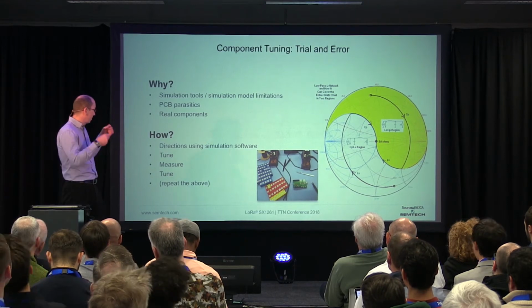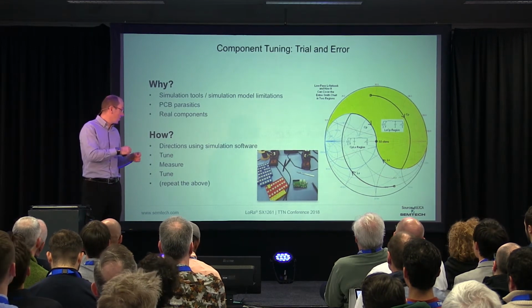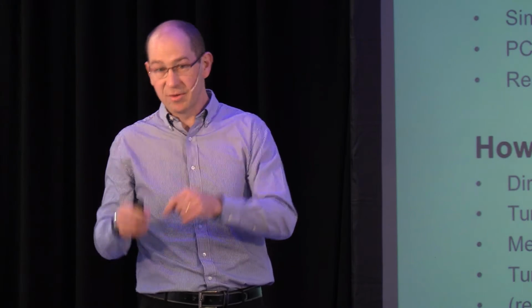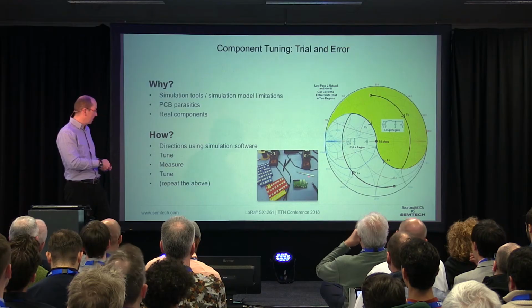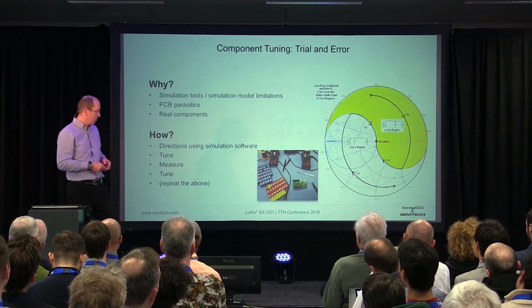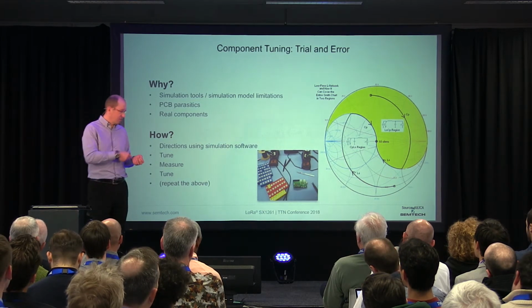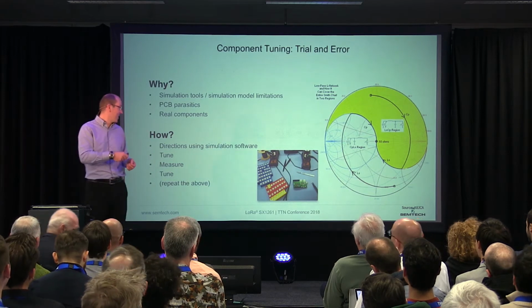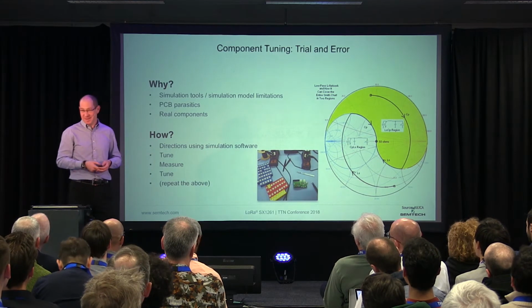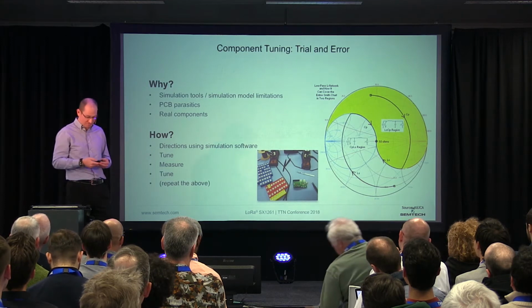It's a tuning process. So you implement components, you measure, modify, measure, and here, be careful. It's not mandatory to use a blade. Don't cut your veins in case it doesn't work. Cutting PCB traces can be useful to implement some probe points.